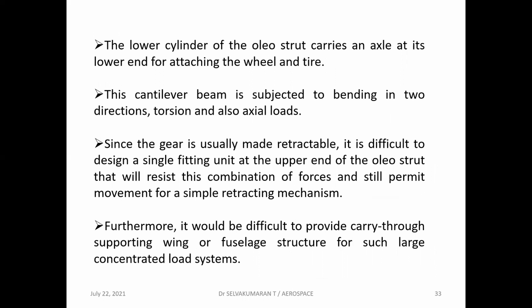Since the gear is usually made retractable, it is difficult to design a single fitting unit at the upper end of the oleo strut that will resist this combination of forces and still permit movement for a simple retracting mechanism. Furthermore, it would be difficult to provide carry-through supporting wing or fuselage structure for such large concentrated load systems.